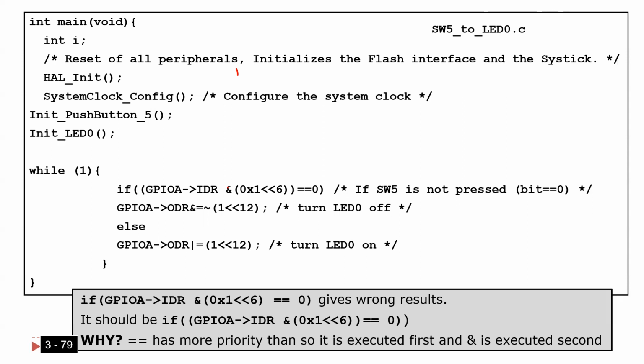So based on this program, guys, normally this LED 0 should be off. Why? Because the voltage here is 0 volt. Okay, so it should be off. Once I press, the pin is going to jump to 5 volt, and the program here is going to turn the LED on. Once I release, the LED is going to be off.